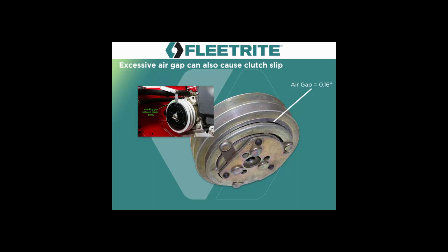A quick way to check those is to use your multimeter. You always want battery voltage at the clutch. So on a 12-volt system, you want that 11.5, 12 to 14 volts of battery voltage. The clutch should draw about 4 amps under load, easily measured with an amp clamp. They can also check the field coil resistance. Unplug the connector, flip the multimeter over to ohms, touch the 2 terminals, and they're looking for, call it 2.5, 3 to 4.5 ohms worth of resistance. As the clutches wear, that resistance factor goes up, and when the resistance goes up, the voltage goes down.